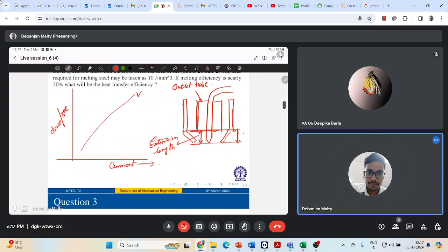Let's say this is one of the voltages. Basically, if you increase your arc current, you also increase your drop transfer, because increasing the current increases the burn-off rate of the electrode. Now, at a constant current, if you increase the voltage, let's say I'm increasing my voltage.